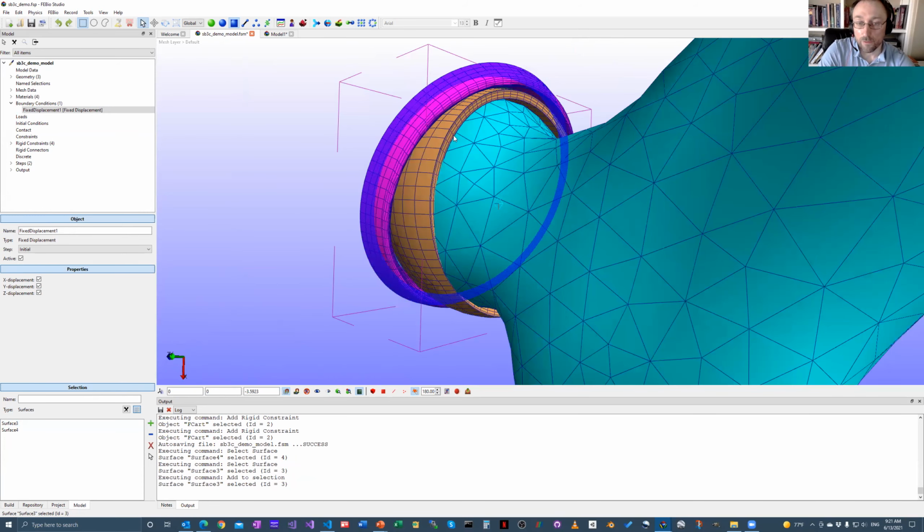And we do that by adding a sliding elastic. Where is it? There it is, sliding elastic. So we'll need two surfaces here. We'll pick the outer surface of the femoral cartilage and assign that to the primary surface. And then I'll go ahead and hide a few things here so I can see the inside again.